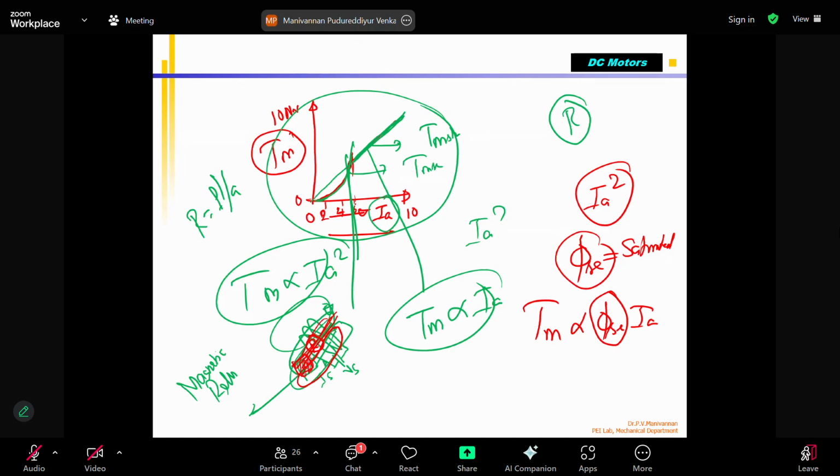Similar to that, here in the armature, everything is made of magnetic material on which you have a coil. Please note that the armature and the field are both electromagnets. It is not just a coil hanging in the air. It is wound over a magnetic material, correct? We have the poles, and then the armature, made of magnetic material, with copper coils through which we supply current.